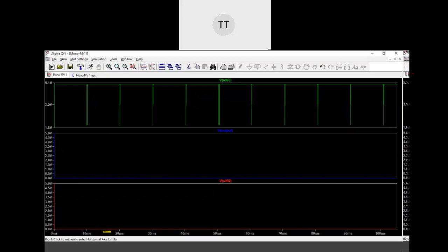Why is the capacitor not charging? It is because the transistor is always on, it keeps on discharging. Correct? So one of the important conditions for the trigger signal is that the trigger signal should always go below VTL. Correct?